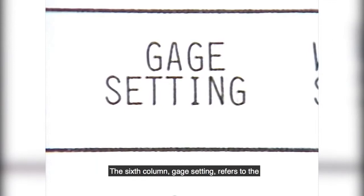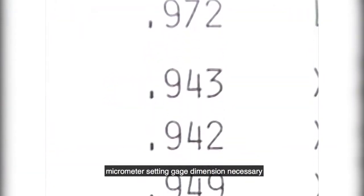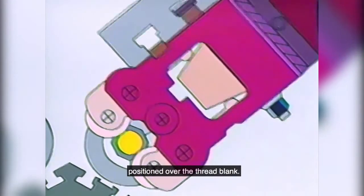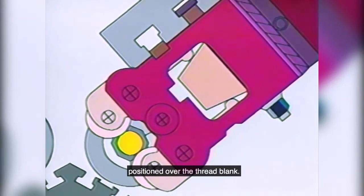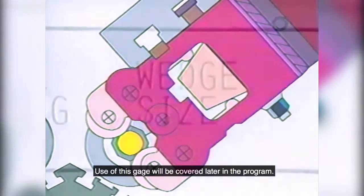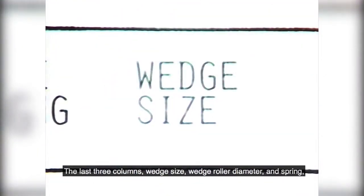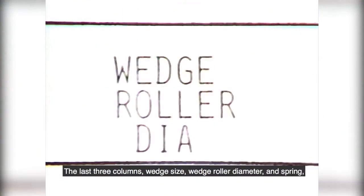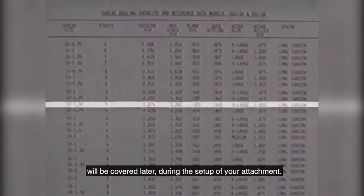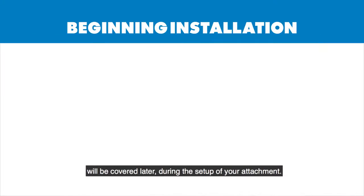The sixth column, gauge setting, refers to the micrometer setting gauge dimension necessary to adjust the cross slide so that when in the full forward position, the attachment is properly positioned over the thread blank. Use of this gauge will be covered later in the program. The last three columns, wedge size, wedge roller diameter, and spring, will be covered later during the setup of your attachment.